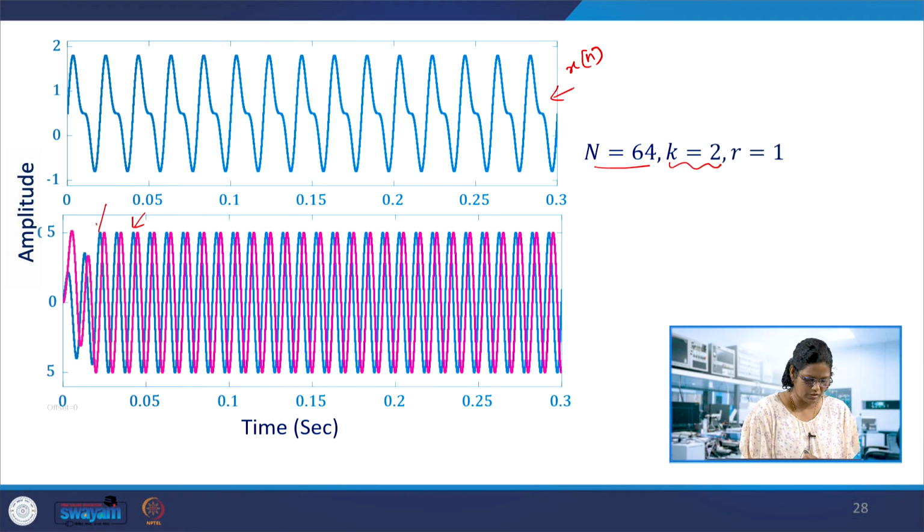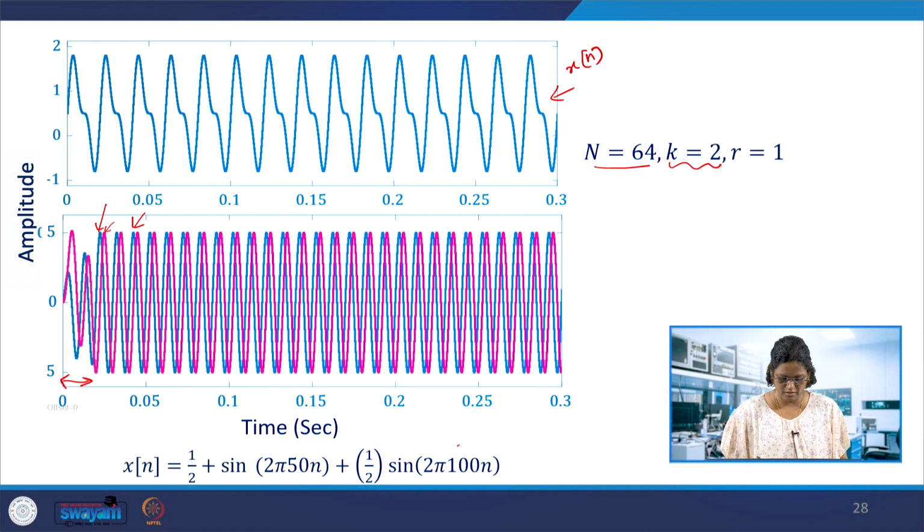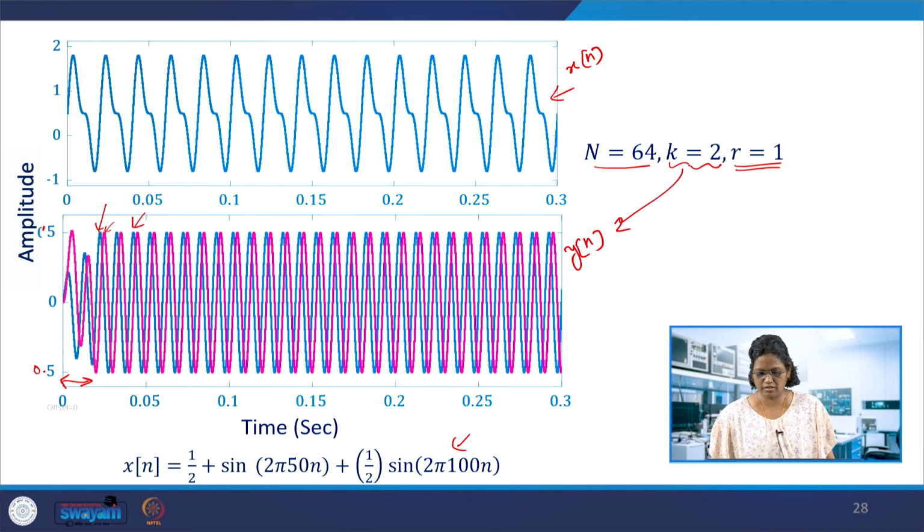Okay. So after n minus 1 samples, that is the transient response. Whichever harmonic it is, the output can be obtained after n minus 1 samples here. So you have the in-phase and quadrature components, that is the real and imaginary converted outputs, shown over here. This is because the signal has a second harmonic in it. R is kept as 1, this is fine. This is y of n for k equal to 2, that is the second harmonic.